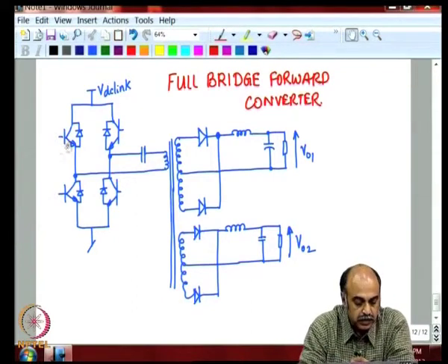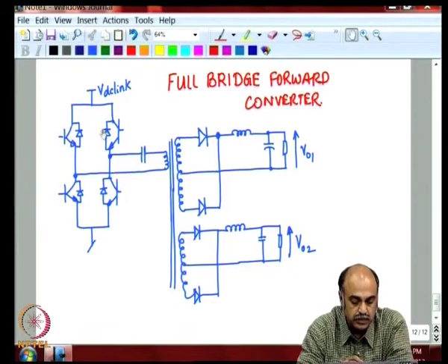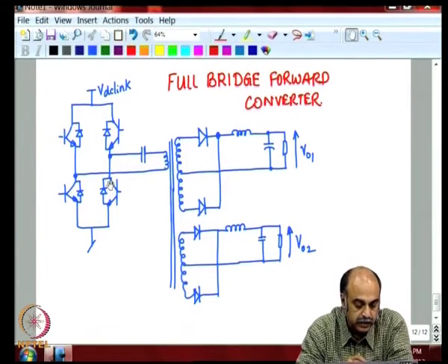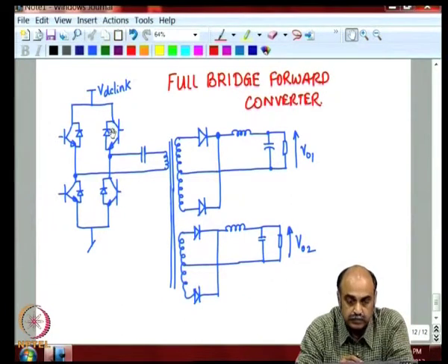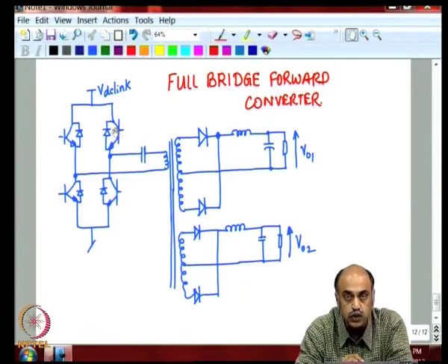In the case of the power semiconductor switches, you need to select them. You are not making them, you are selecting them from the manufacturer's data sheet. So, what information would you need? You need to know the current stress, the voltage stress and the thermal stresses occurring in this circuit topology, and appropriately choose a proper device from the manufacturer's data sheet.